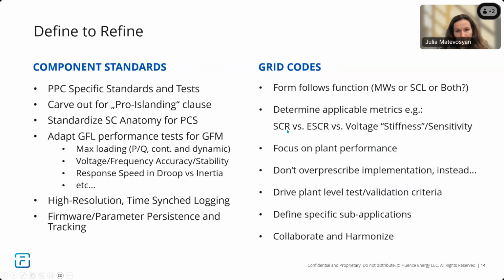Mm-hmm. So I think even just the short circuit ratio that I've hit on a couple of times, there are also different variants of short circuit ratio. You'll see maybe equivalent short circuit ratio, or there are different methods for calculating it. I've seen talk, and even myself years ago on isolated systems, of a reactive inertia, almost just to draw that parallel to the inertia on frequency. Voltage stiffness, as I've mentioned here. I think there are a lot of papers. I don't know if I would necessarily advocate for one or the other.